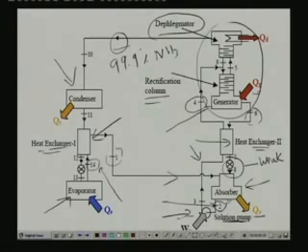So, this 99.9% ammonia vapor, which is at high pressure and high temperature, goes to the condenser. It condenses in the condenser by rejecting heat of condensation QC to an external heat sink, and it becomes a high pressure liquid at 0.11, and the high pressure liquid at 0.11 now flows through the heat exchanger, where it rejects heat to the vapor coming from the evaporator. So, in this process it gets subcooled. So, at 0.12 you have subcooled refrigerant liquid still at high pressure.